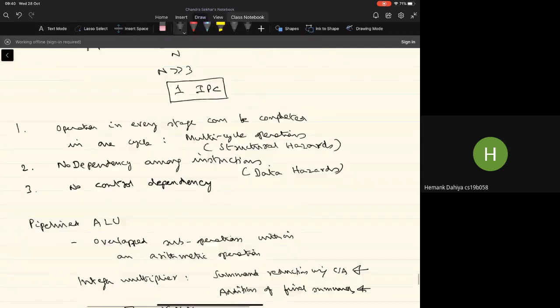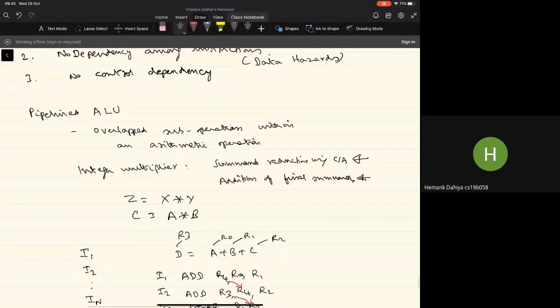And these kinds of cases are referred to as what are known as the control hazards. So this is typically associated with all the jump instructions or the call instruction, right? And when I say jump instructions, it can be unconditional jump instructions or conditional jump instructions.